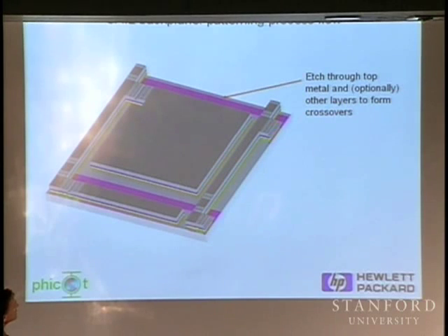And here's the trickiest part of this process. Now I actually do an undercutting process. I continue to etch this aluminum until, actually, that was done in the first step. So everywhere, underneath these little grill works, is the gate metal, because that was undercut when I cut down in the first step to the gutter, and that cut through there.